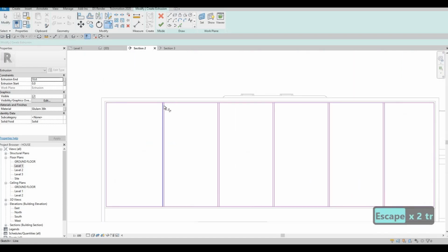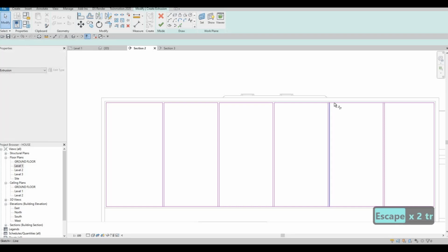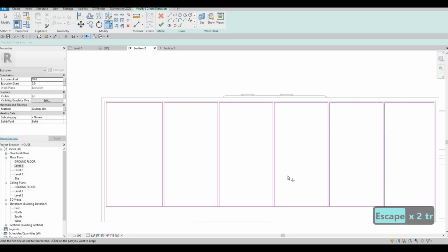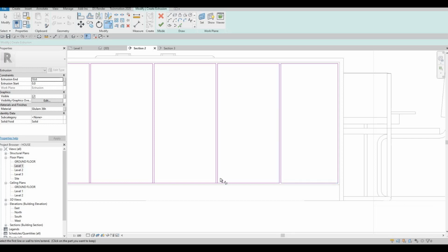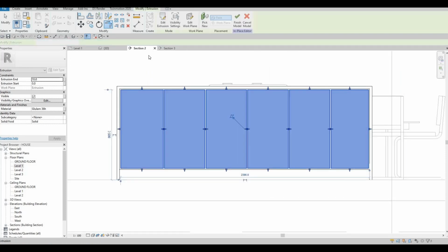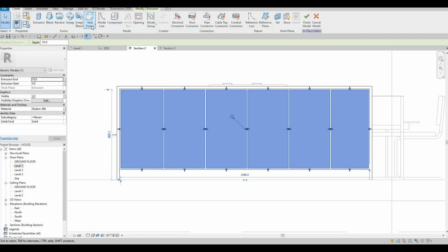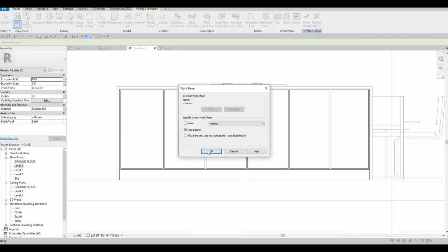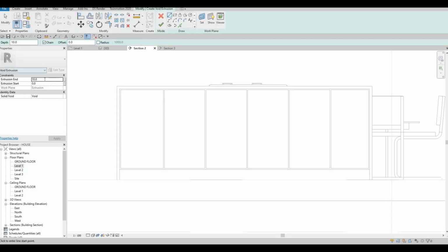And then trim and extend. And then here as well. So click finish on that, and then click create void form extrusion, and then pick this one again, and then now we put 5 and then -5 here. Apply, and then here 50 as well,